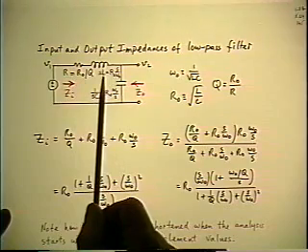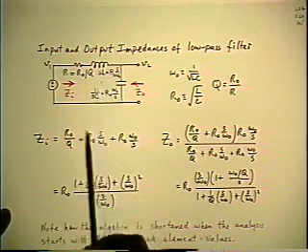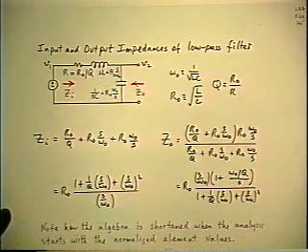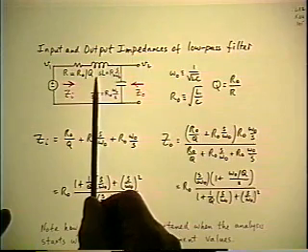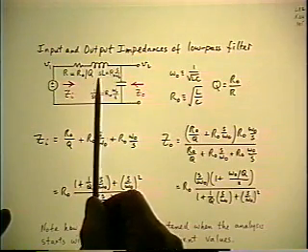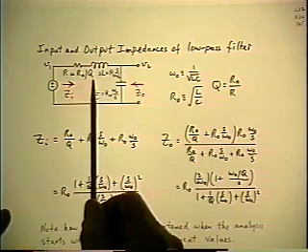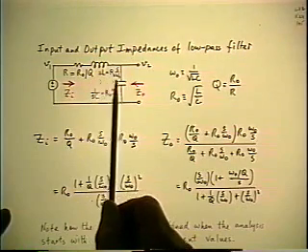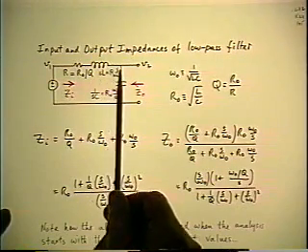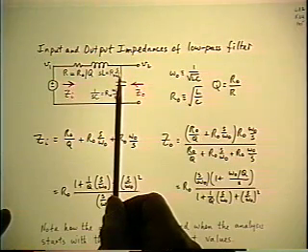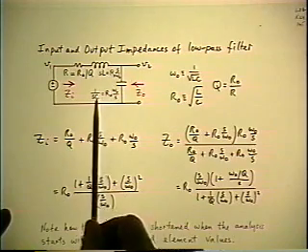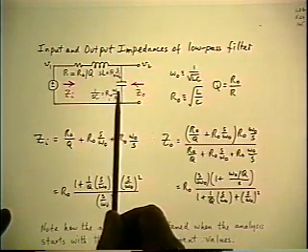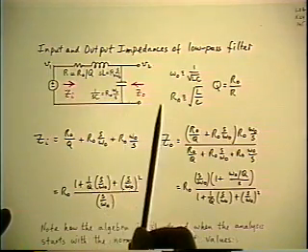Do the same thing with the inductance, except you can make an additional anticipation here, because what we're going to want in the answer is not the inductance itself, but the inductive reactance, namely sL. So put that in as well. So the inductive reactance sL turns out to be R0 times s over omega 0. And similarly for the capacitive reactance, 1 over sC, that becomes R0 omega 0 over s.